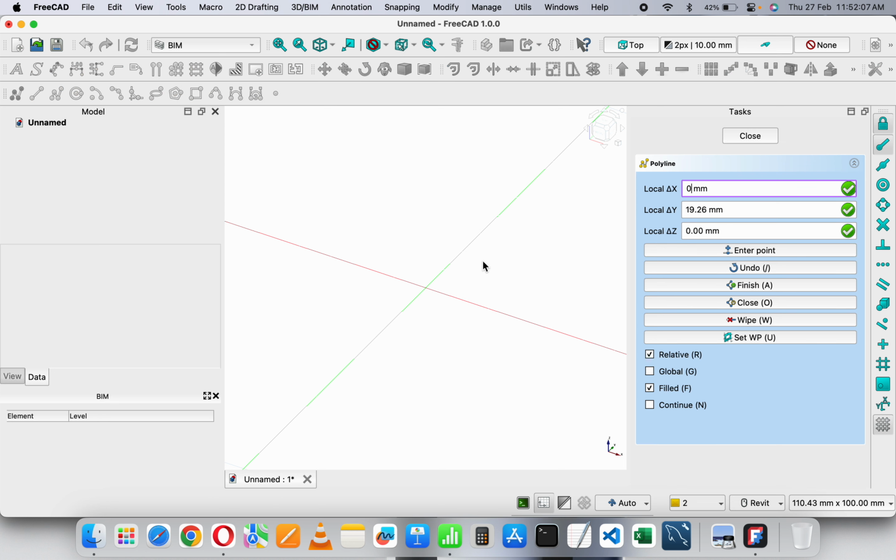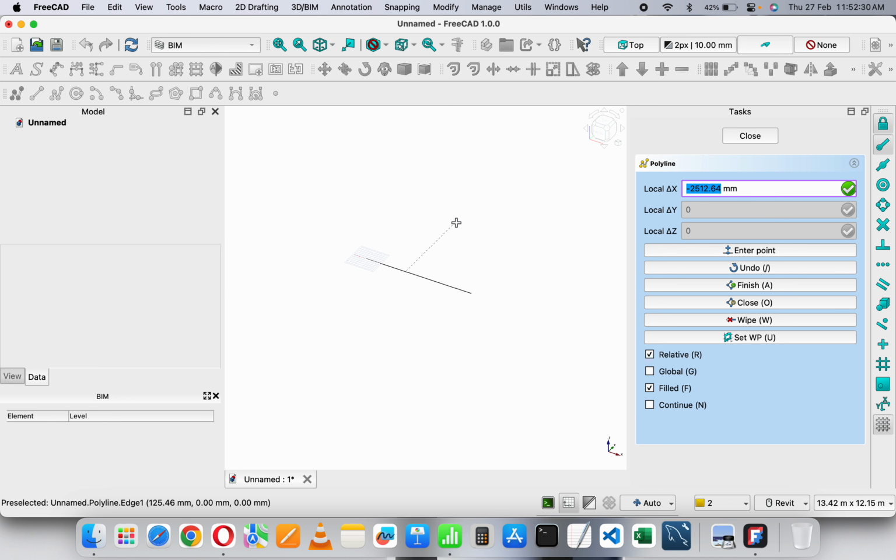First of all, origin is 0 for all. Click enter, and then along x-axis press X. The x-axis will be locked. Now along X put 4000 millimeter, that is 4 meters, the first point. Okay, click enter. After that, the x-axis is locked. Again press 4000 millimeters and press enter. Now those two portions are created, and now click close.